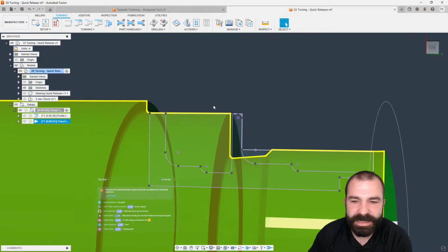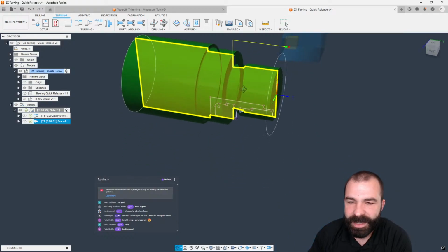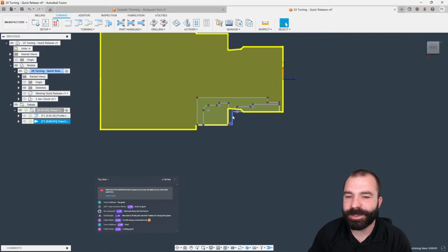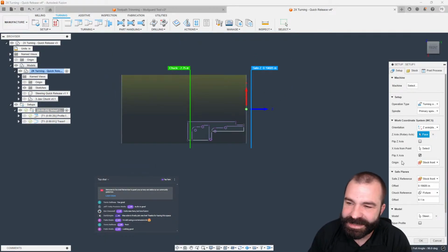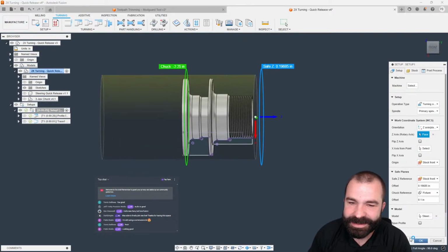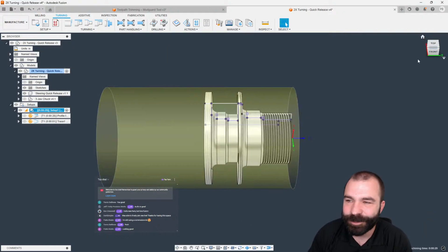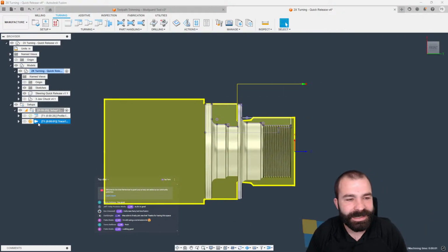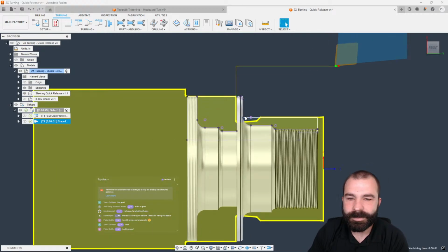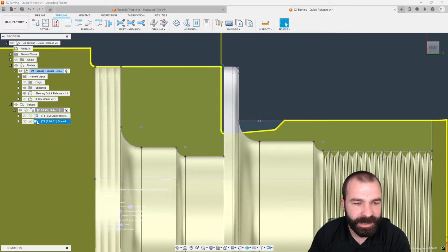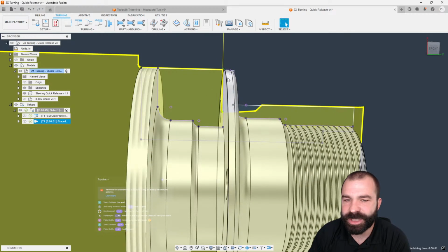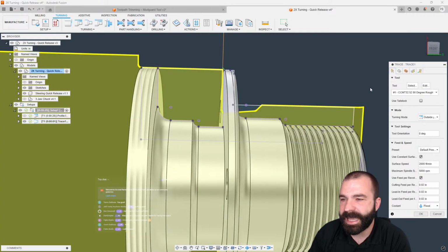As you're going to see here, that's going to calculate out. And again, this is going to look very weird for a lot of you out there because we are dealing with the sketch opposite of our toolpath. If I would stop being lazy and difficult, we're going to go ahead and flip our x-axis. Now our toolpaths will follow our sketch, to get our tool on the right side. There we go. Now again, what's happening here is based on that toolpath and based on the sketch selection, the tool is following exactly that, right?